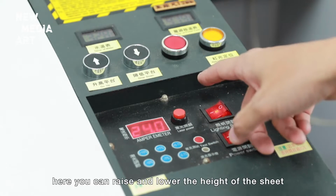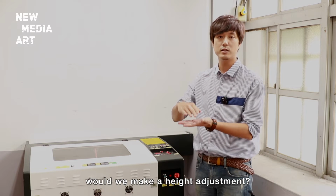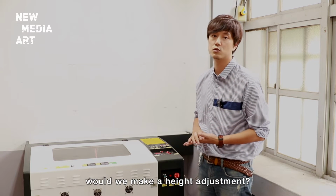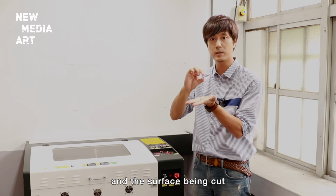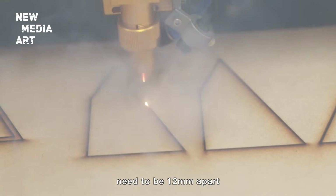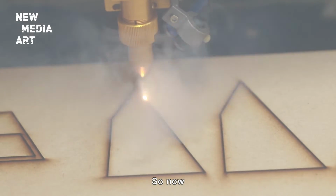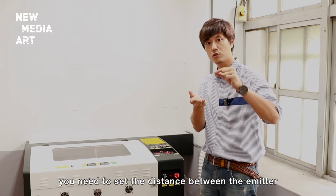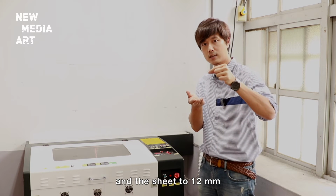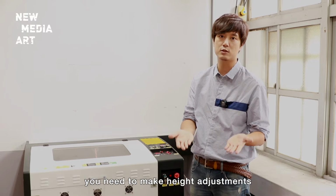Also, here you can raise and lower the height of the sheet. Why would we make a height adjustment? Because actually, the laser emitter and the surface being cut need to be 12 millimeters apart. That is the focal point of the laser. So now, no matter how thick or thin the sheet is, you need to set the distance between the emitter and the sheet to 12 millimeters. So this is why you need to make height adjustments.